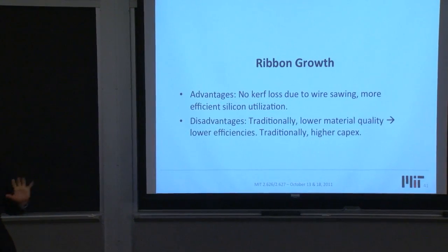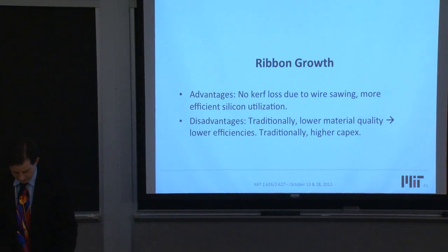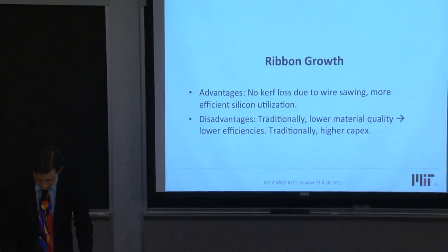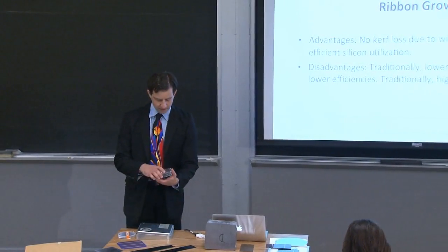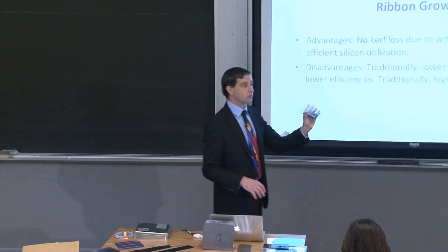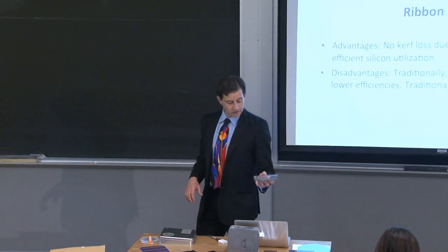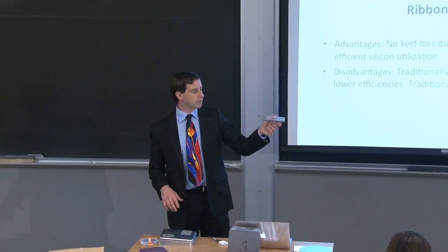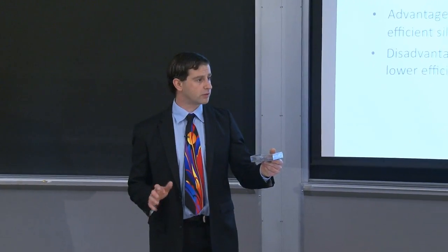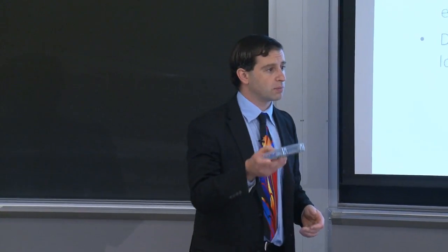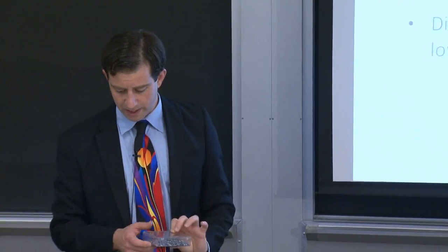And what we've done, just to resituate ourselves, we talked about the silicon feedstock, right? So we chatted about how you go from quartz in the ground and the carbon-bearing feedstock material to the purified, heavily purified silicon feedstock material. This right here is probably on the order of somewhere between 8, 9, or 10 nines pure, very, very pure material. This Siemens grade polysilicon right here in my hand.